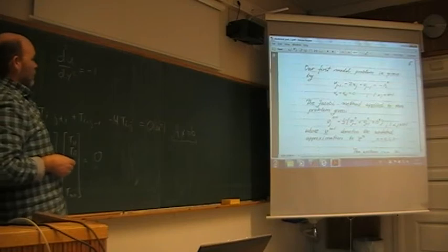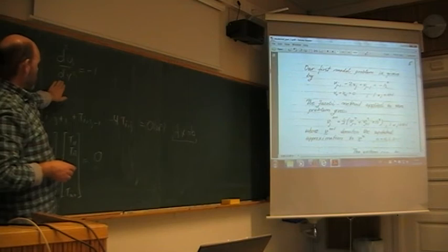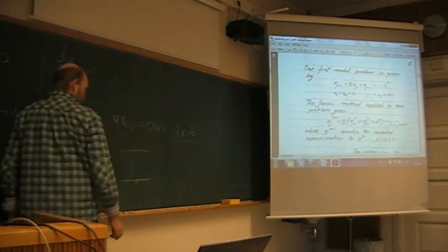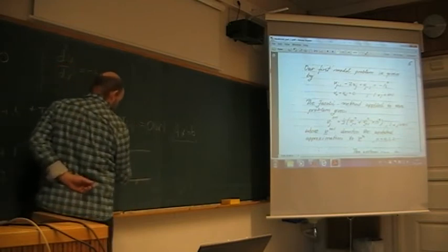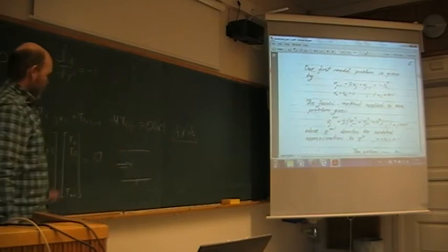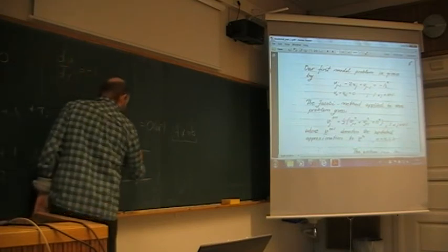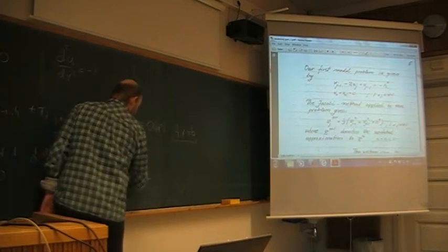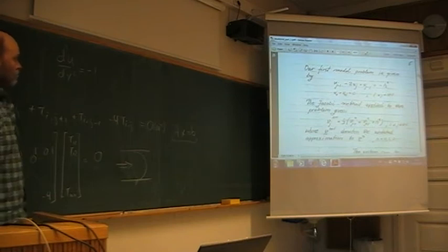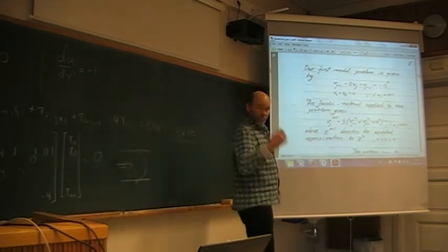Which then should be something like the Poisson equation, for instance, meaning you have the flow between two parallel plates, and then you insert a pressure to make it flow to the right, and you have a negative constant pressure gradient, and then you will get the solution, double derivative equal to -1, should be something like this. So you know the solution here. H then here being delta y.